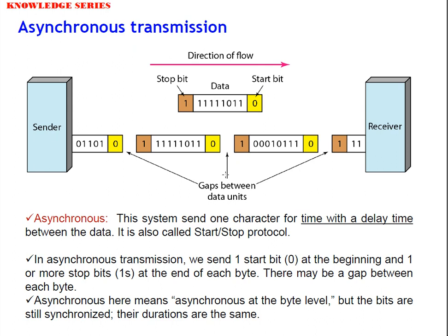Before understanding this, let us see how an asynchronous bit is being represented. Any asynchronous frame will have data bits surrounded with a header and a trailer. The header is a start bit, the trailer is nothing but a stop bit. So here you can see a 10-bit transmission.